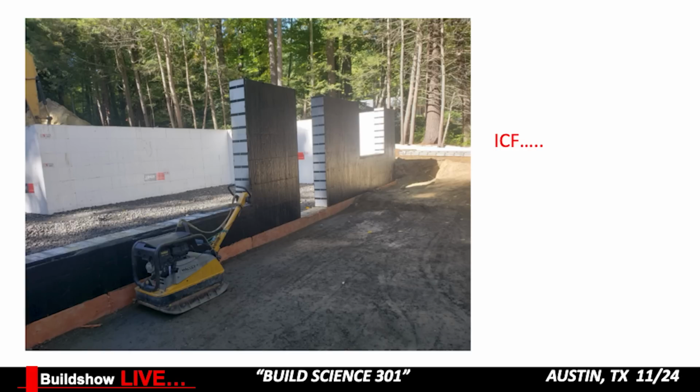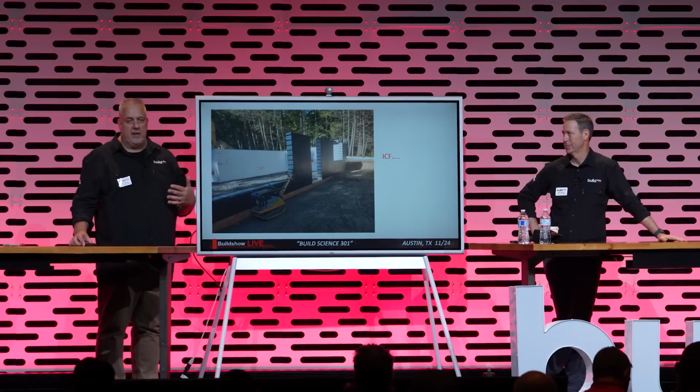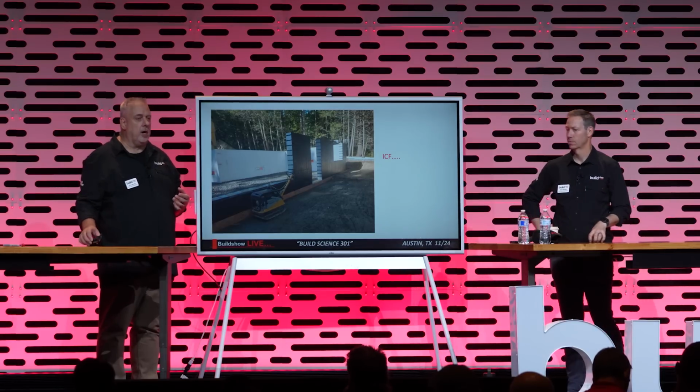So it's also a protection board, right? It's there to provide the drainage medium, but it's also there that if we drop a few rocks in, we're not damaging that ICF or damaging that waterproofing.